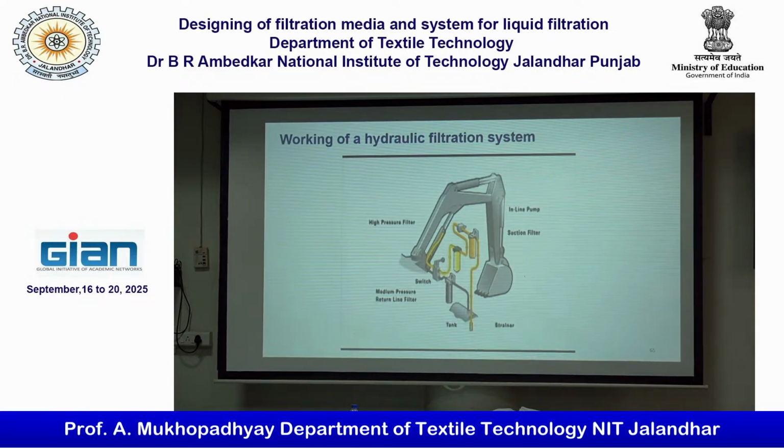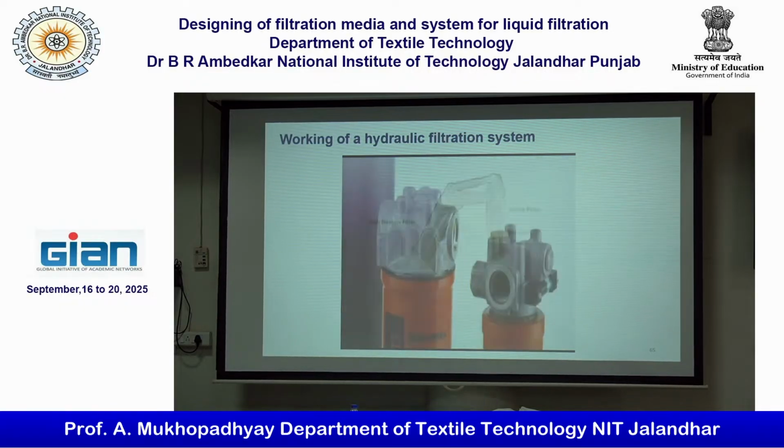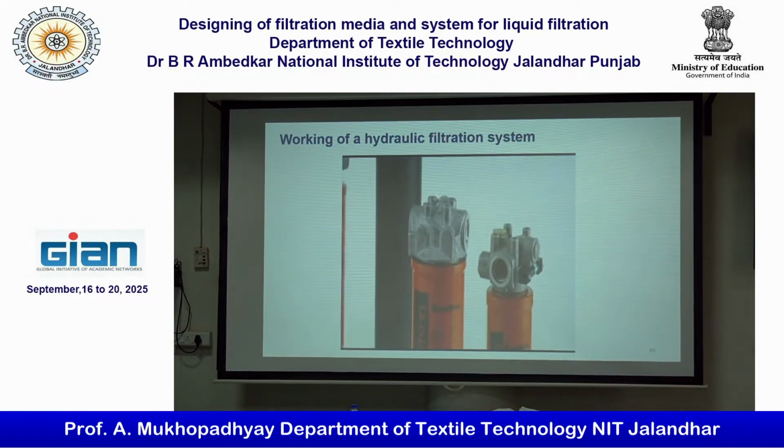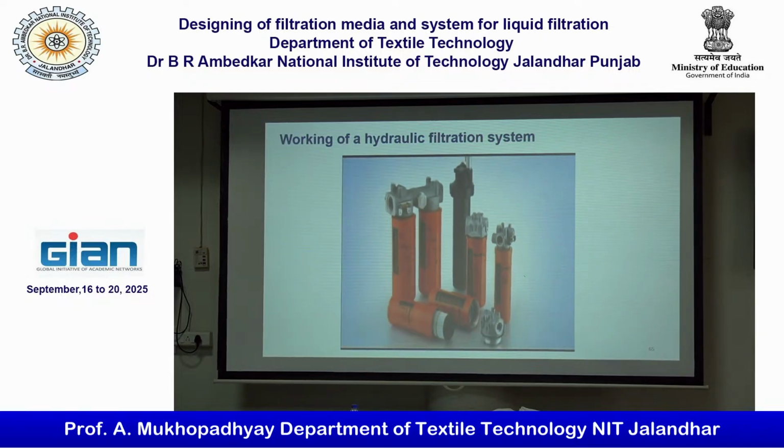After doing its work, the hydraulic oil proceeds back to the holding tank. It first passes through the medium pressure return line filter, which removes contaminants generated during component activity. Ideal for medium pressure application in the circuit is the Donaldson Duramax series.